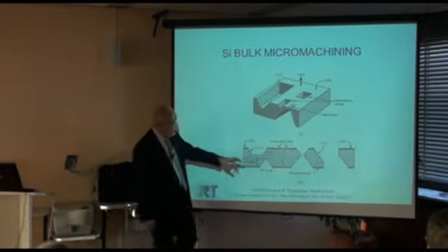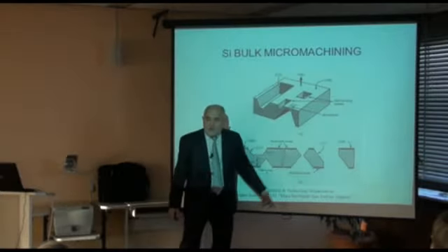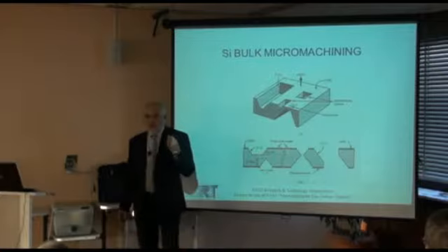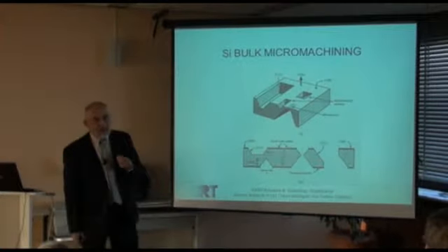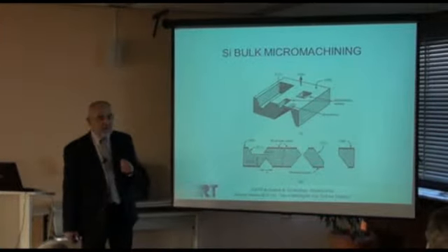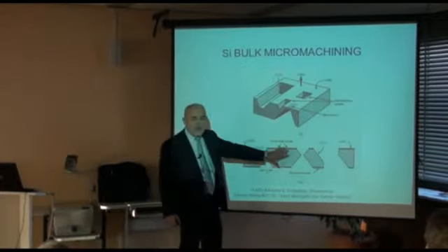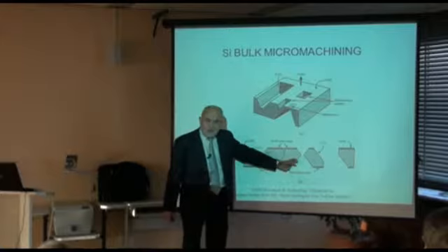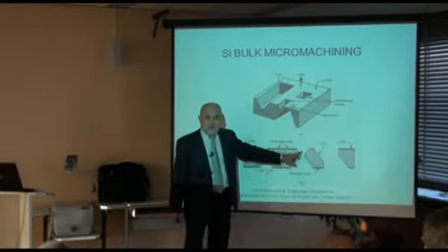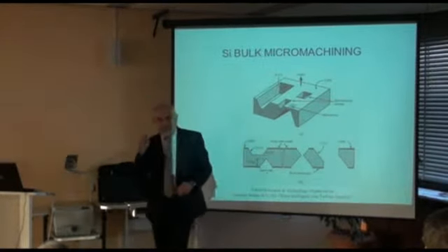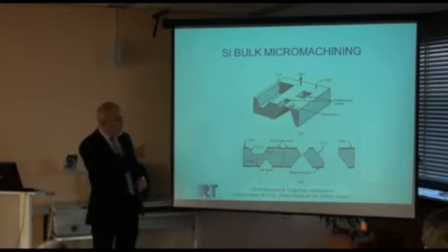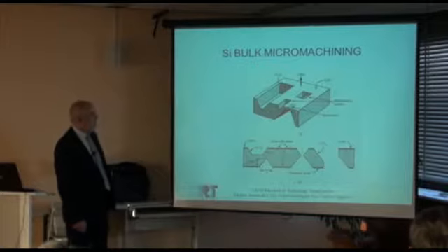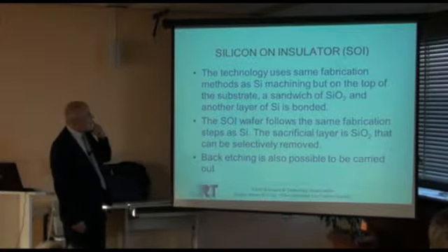One could also make through holes, and by the way, these through holes are the core technology for inkjet printing heads. All the inkjet printing heads are made in this silicon technology. The wafer is thinner, but the nozzle is lighter, and all the droplets of ink come out through that nozzle, a convergent divergent nozzle.